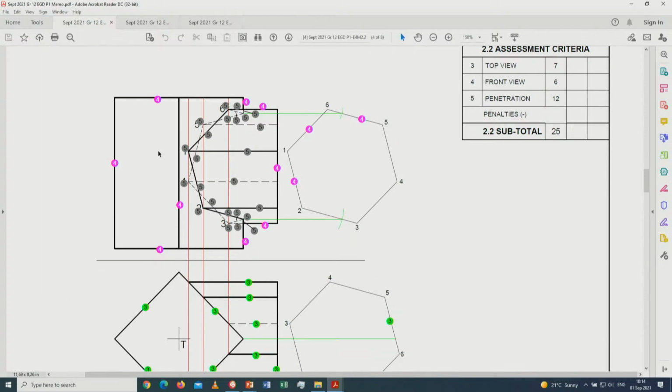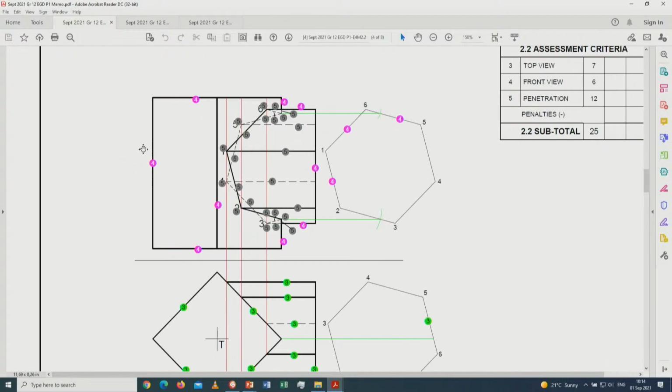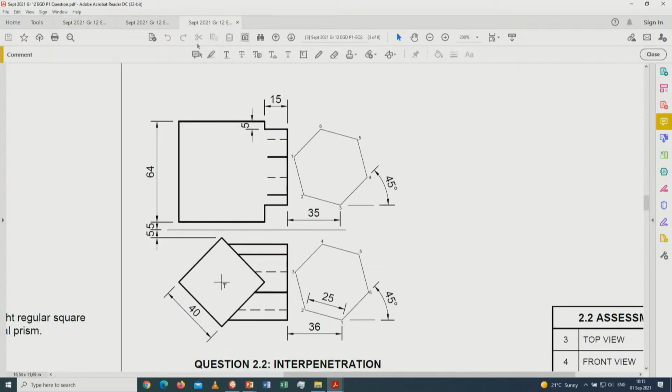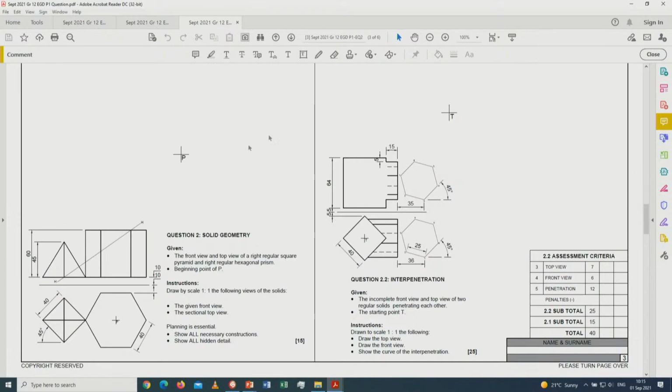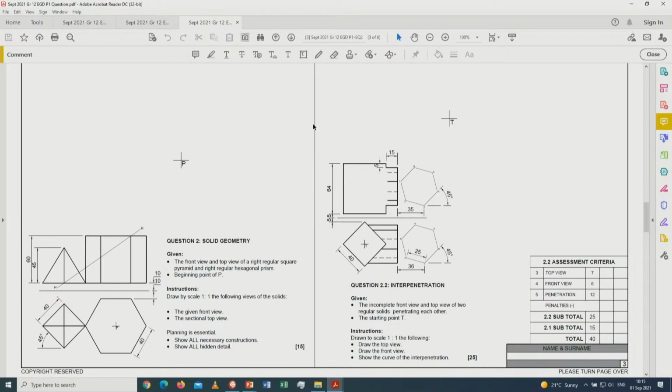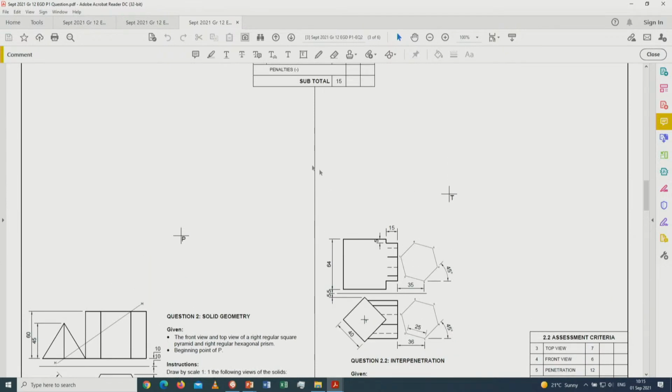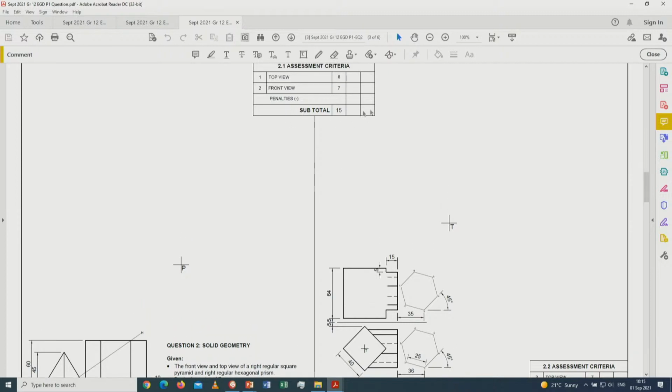The learner could have also done a right view in this case because of giving you a solid line over here. But now, if it does so, if you go back to the question paper, on his sheet, it will go into this area over here. So therefore, you will go into this area, which is not wrong. You can't penalize the learner for going into this area over here. So that is still basically the correct method in doing so. So that will be from the top view 45 upwards. So you will most probably go over this line over here to find the fold lines, to find the bend points or the bent lines where it will be bent into the next part over here.